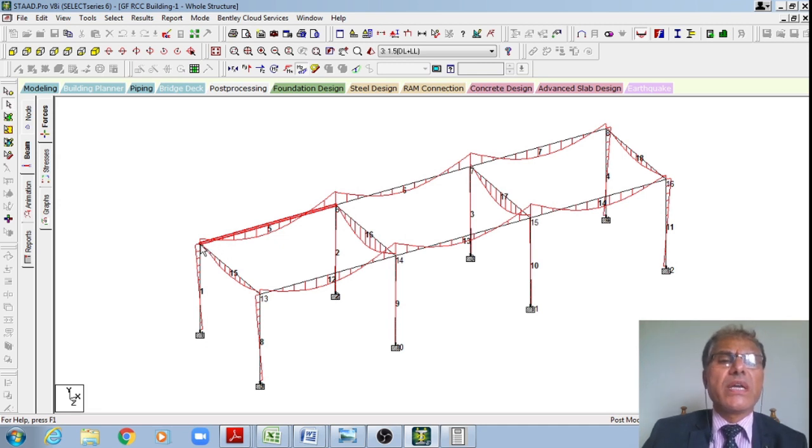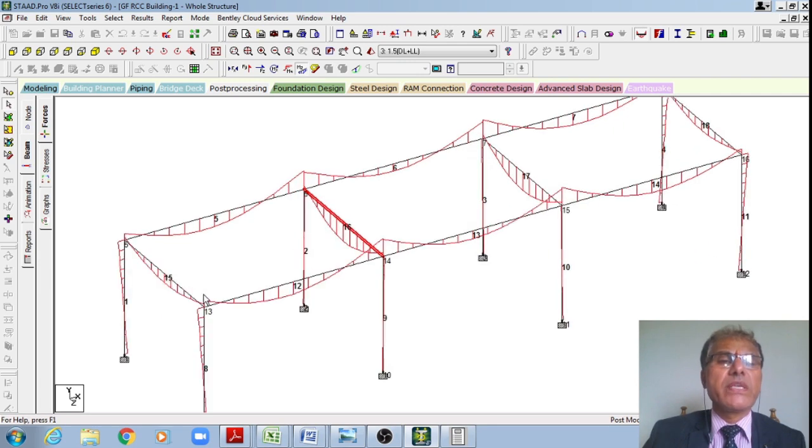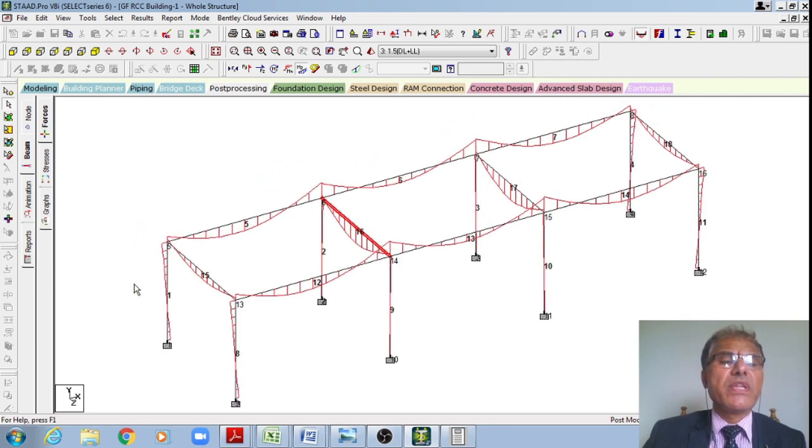That is how we can see negative bending moment at the continuous support, positive bending moment, negative bending moment, positive bending moment, right? That is how the variation of the bending moment along the three-span continuous beam, whereas then bending moment variation for the exterior beams as well as the interior beam. Now even you can see the variation of these.